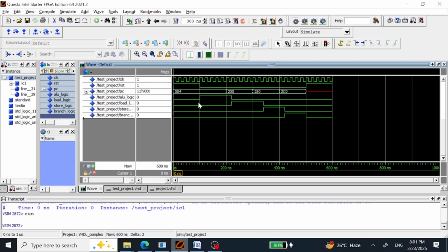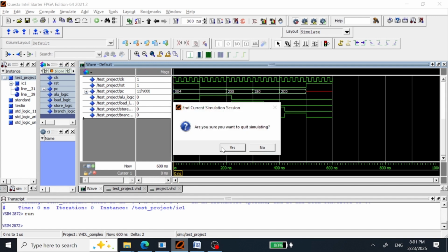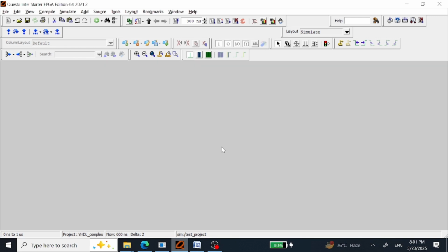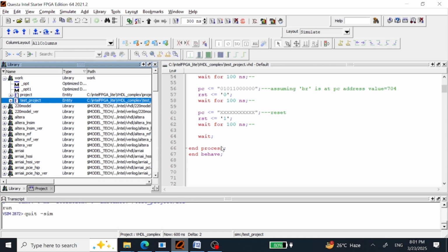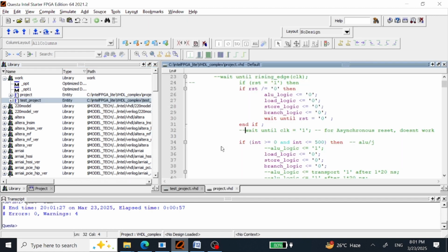Now you see here, the signal is getting extended. The signal is getting extended here. Instead of getting delays, we are getting this signal extended. So this is just another thing which I wanted to show you, the way the loops or the repeat statement in the case of SystemVerilog run and how they give you the delays.